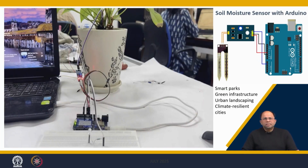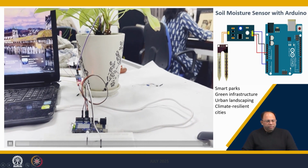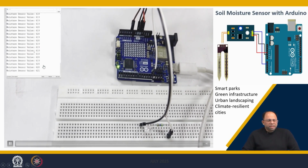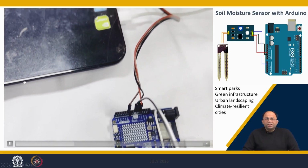So here you can see the setup that we have done. We are using a breadboard, then you can see the Arduino Uno board, and then there is the comparator over here, and then the actual probes are inserted into the soil over here. And to show you, first, I will show you the value. This is the setup, and you can see the sensor value is coming around 619, 618. That is when the soil is not dry, but it doesn't have that much moisture as well, right? So that is the initial value when we are measuring.